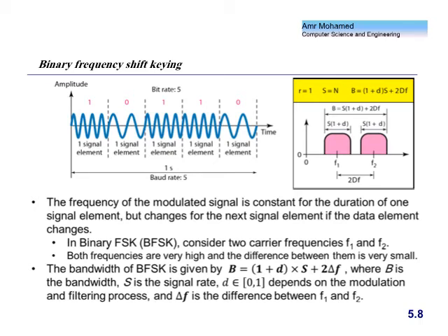So I have to have 2 frequencies. The number of frequencies here equals the number of bit combinations that I have. I have 2 states, then I have to have 2 frequencies. So as we said here, the more I increase 2 delta F, the better the quality will be, but the bandwidth will be increased. So make it small. Okay? What is the smallest value of 2 delta F?